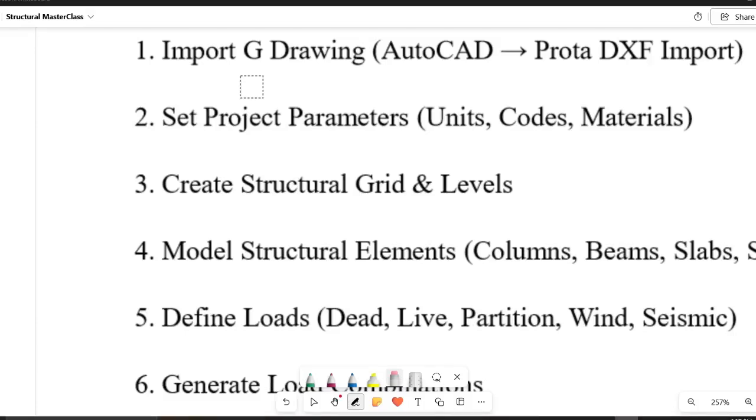Maybe you are designing your beams or structural members with rebars that do not exist. Like in my country, we don't have bar D13 or D14. You have D12, you have D16. So you have to tell the software the practicalness of your model. We are learning about real design. So these first three steps will help you come up with very realistic designs or members, which will translate to very realistic drawings.